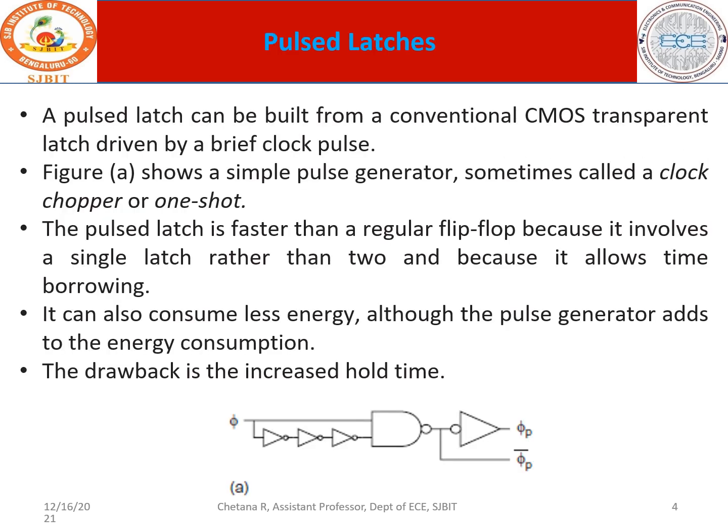Look into this topic called pulse latches. What exactly is a pulse latch and what is its construction based on? It can be built from a conventional CMOS transparent latch driven by a brief clock pulse. So you have the conventional CMOS latch which is driven by a clock pulse. The figure shows the simple pulse generator, which can also be called a clock chopper or one shot.